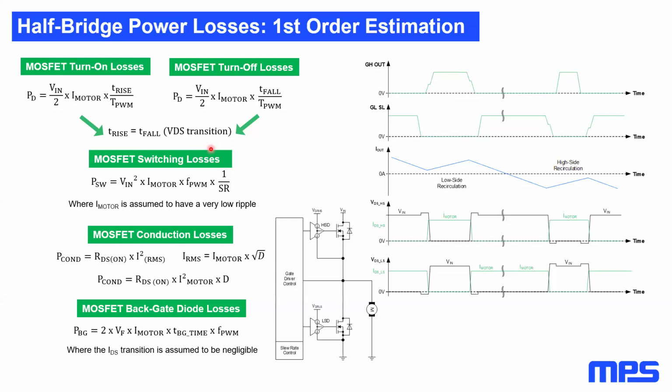These operations are called soft switching. So soft switching is when the MOSFET turns on while its body diode is carrying the current, and hard switching is the opposite, when the MOSFET has to start carrying the current from the neighboring MOSFET, let's say.